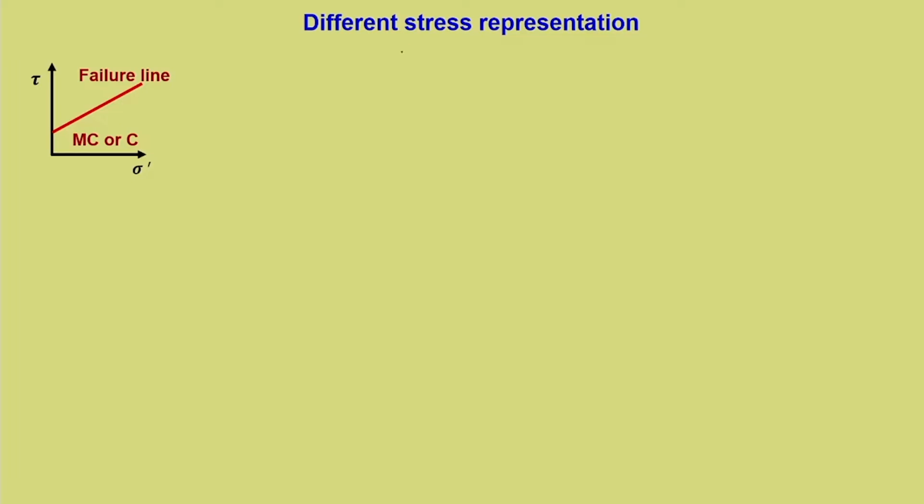Now, this lecture is a continuation of that one. We have represented the stress in terms of shear stress and normal stress. There are various other ways of representing stresses for different failure criteria. So, in this lecture we will see the different representations of stresses for defining the failure of a material. The first topic is different stress representations.